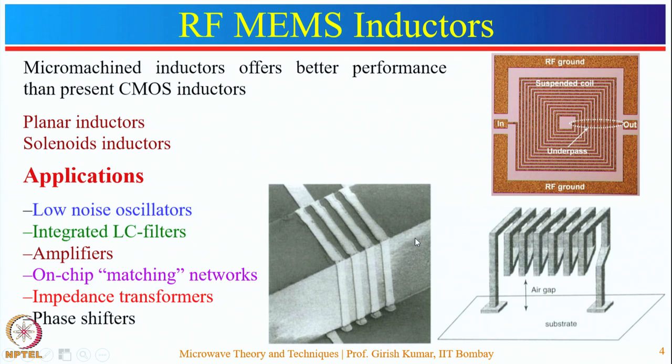Now, the losses in the core occur because of two reasons. One is the capacitive coupling, which occurs due to the conduction current in the metallic strips and the current between the metal and the substrate region. The other is due to the inductive coupling, which is due to the current loops and the magnetic field which flows between the metal and the substrate, and this provides the losses, and this reduces the quality factor of the inductor. The quality factor of the inductor can be improved by narrowing the inner turns and by widening the outer turns.